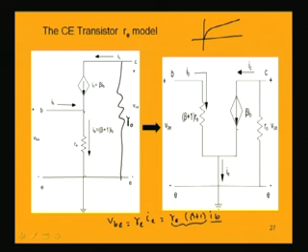So, now at this point both IB plus IC are meeting. So, IB plus IC is here, and this is a far better circuit than this, because our main problem was at this point these two are joining and this current is not IB, it is IE. So, it would have led to some difficulties in analysis. So, we have conveniently removed the difficulty by drawing the circuit in this fashion, and it will be now easy, because you can now notice that input and output circuits we are conveniently separating out. So, this is done by writing the equivalent or reflected resistance for this RE, which is nothing but (beta plus 1) RE.